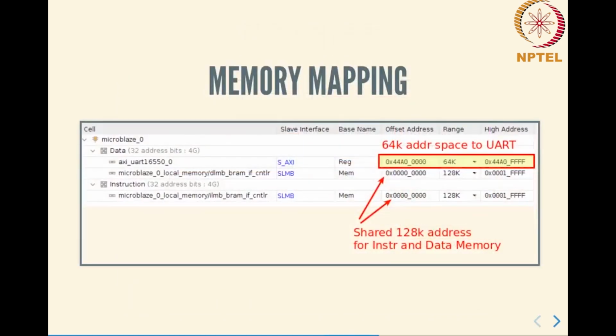Now, how does a processor actually communicate with the peripheral? We have seen that a system bus is used in order to connect the peripherals to the processor. And in addition to that, we use something called memory mapping, where a portion of the address space of the processor, that is, some of the addresses that the processor can potentially talk to, are used in order to map parts of the peripherals so that when the processor reads or writes from those addresses, it is indirectly talking to those peripherals. The figure shows an example memory map.